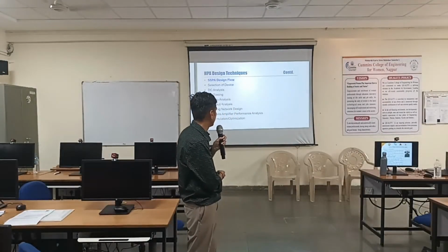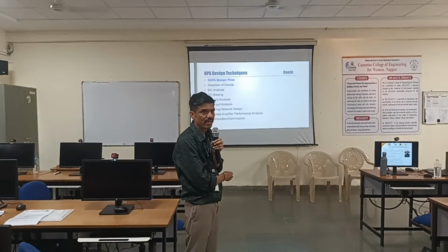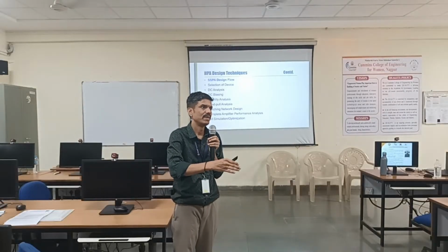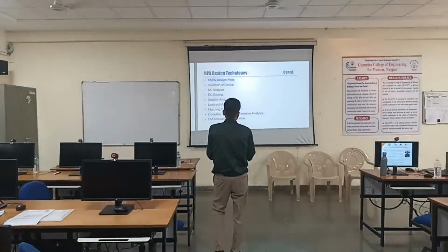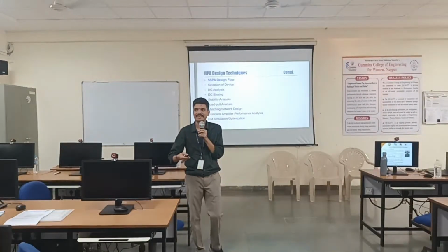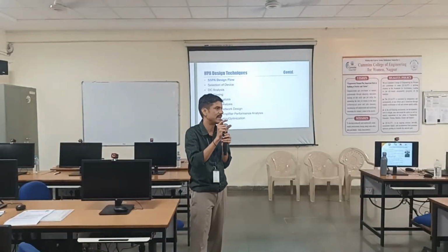Then we have to do load pull analysis. For what purpose? If you are following till this time, you will appreciate the meaning of this. Who will tell you the input impedance and output impedance of the transistor? We said that we have to design a matching network.